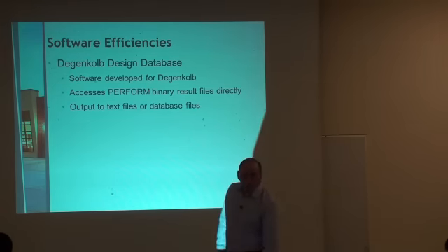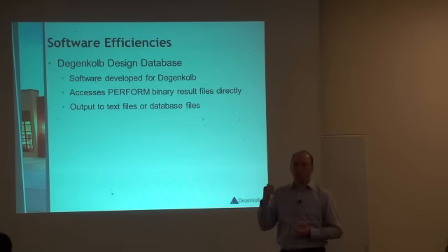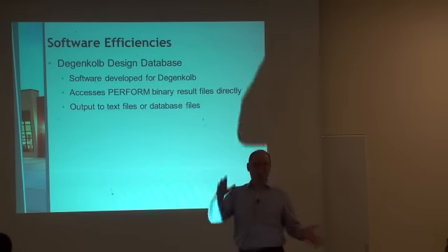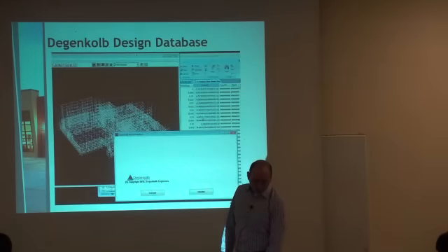And while something like this may not be that badly needed with OpenSees, because OpenSees has good reporting capabilities, with Perform, it's a must, because all results are dumped into a big binary file. And to go and process these results through the user interface would probably take you a year to do.